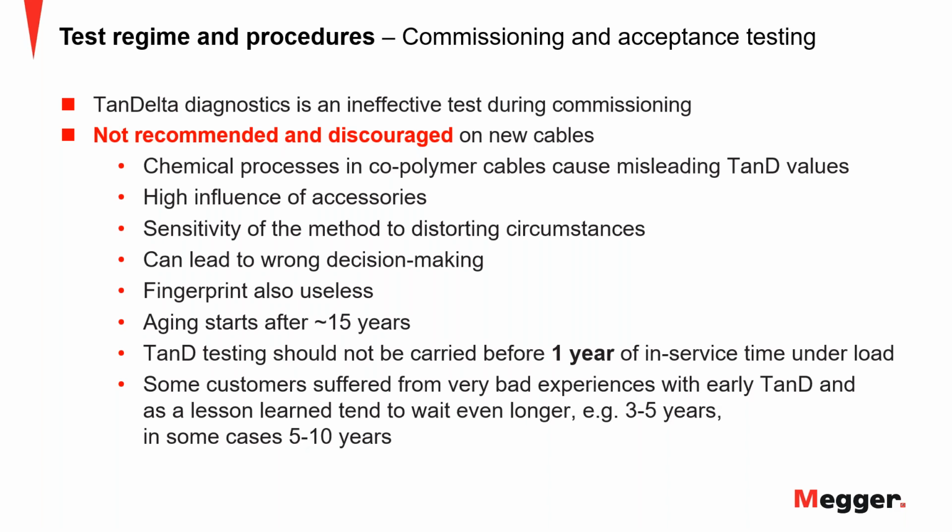The reason is today all of the cable is copolymer cable, tree retardant XLPE cable. And these cables, they show a certain behavior long before you can actually call them aged. So when we're talking tree retardant XLPE and you say aging, we're talking 15, 20 years. Before that, it's not aged, forget it.